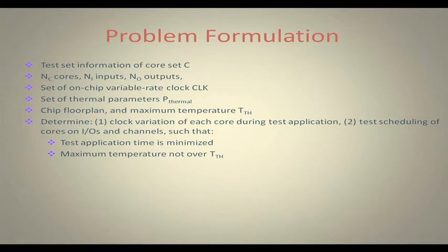They are actually the thermal parameters, like the dielectric thickness, the heat spreader, the size of the heat spreader, the size of the heat sink and all that, so that we can do the thermal simulation. Then the chip floor plan and the maximum temperature T threshold.